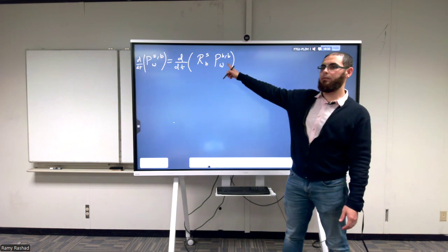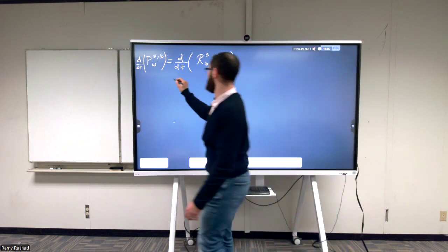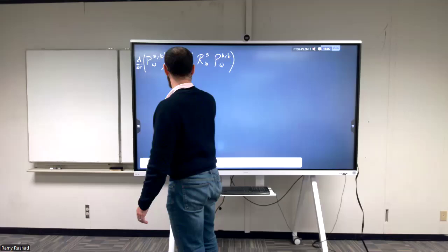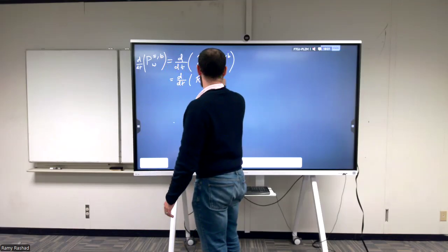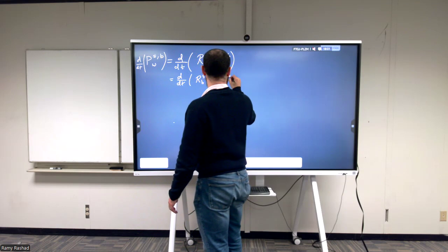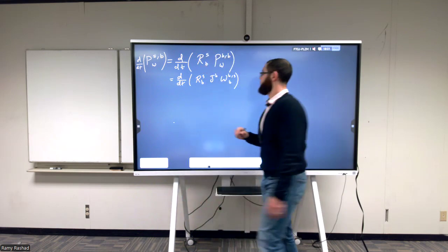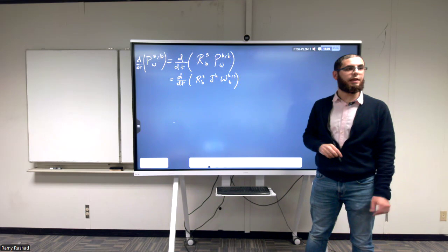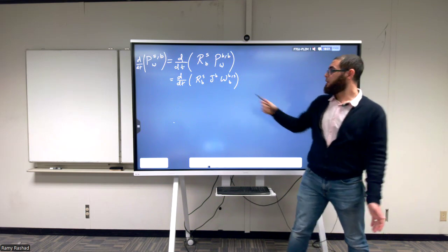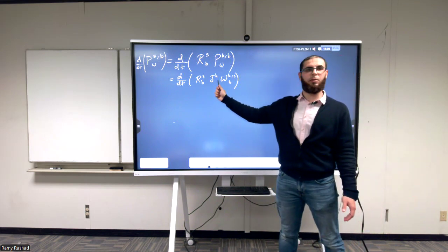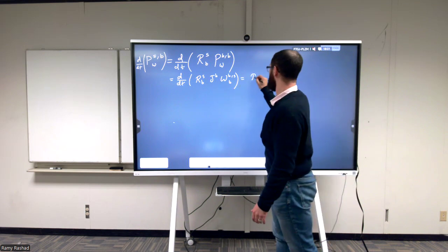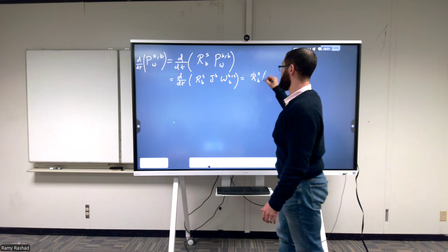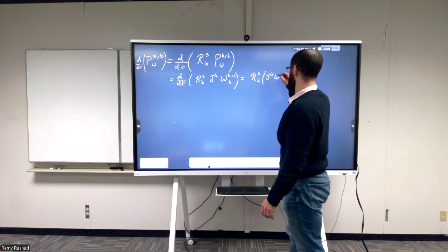Then I'm going to substitute this term by JB omega B like that. And then I can differentiate. This term is constant when we see it from the body fixed frame. So we simply get that we have R dot BS multiplied by this term,